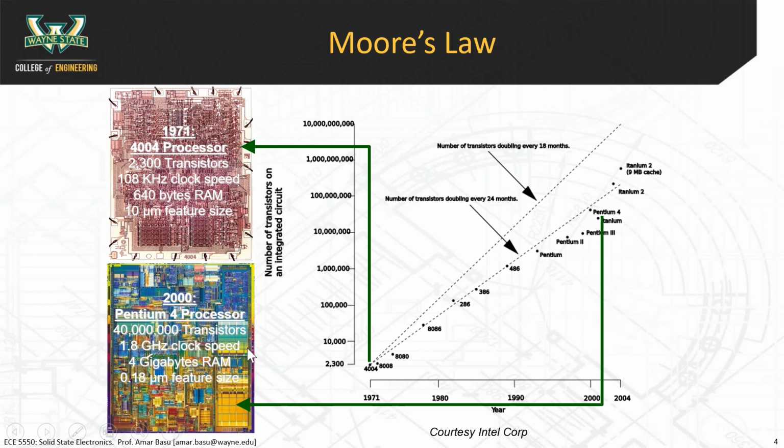When you have a smaller transistor, it takes less time for electrons to travel through the device because there's less distance to move. And you can also think about it in terms of capacitance. We're gonna talk about the gate capacitance of a MOS capacitor. So we'll get into that later. But basically, as you make the transistors smaller and smaller, it turns out they work faster, and you're able to cram more and more into an area.